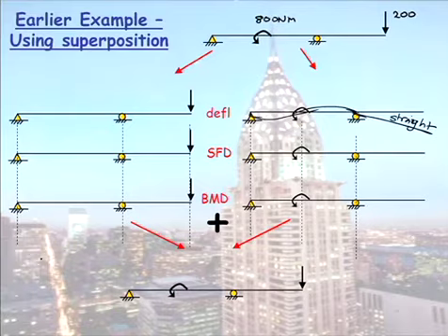So my shear force diagram there, based on that quite ugly deflected shape I drew for you, if I took this pin support away, which way would the beam want to flip? Up or down? Down. Therefore we know our reaction here will be upwards because it's not flipping down. And if I let go of this roller support here, which way would it want to move? It would flip up. So the reaction here must be down. And in order to get forces in the y direction equal to 0, you know those 2 forces are equal and opposite.